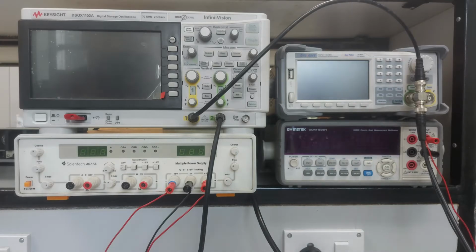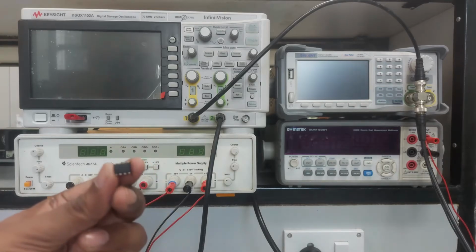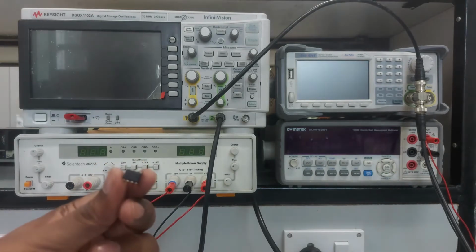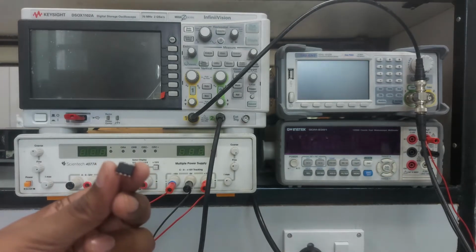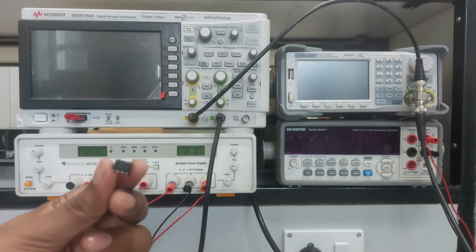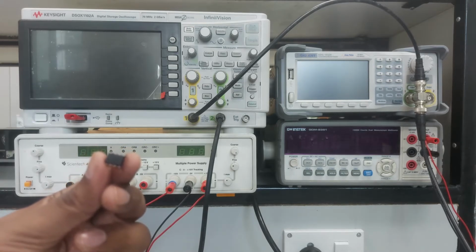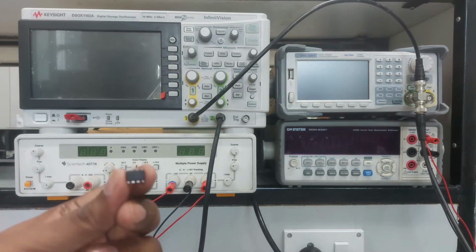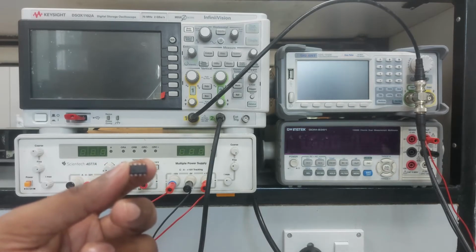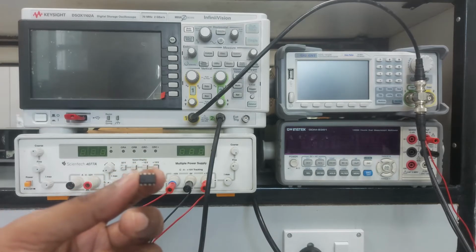At lower frequency the gain will be very high, that is 10 to the power 6. As we increase the frequency, the gain will roll off, the gain will decrease. For the 741, it is minus 20 dB per decade. Decade means an order of 10, right? So the frequency increases in decades, and the gain will decrease by 20 dB in each decade, like 100, 1000. Suppose the frequency is 100, then the gain comes down from 10 to the power 6 at the 100 frequency.